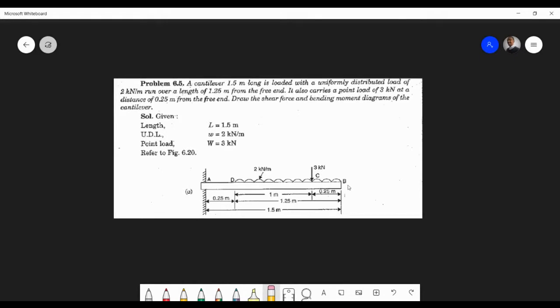No, remember, it's 0 at B on the free end. The moment would be a max at the fixed end. Just think about a ruler fixed, bending downwards. You experience a maximum bending moment at the fixed end.